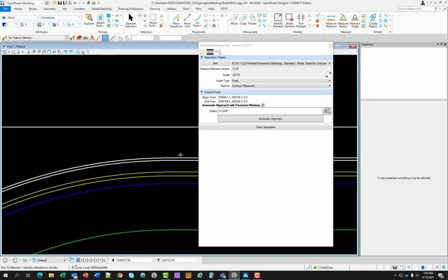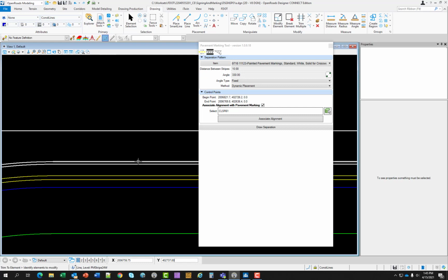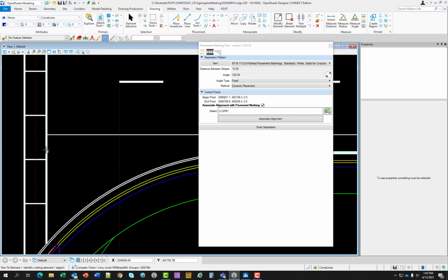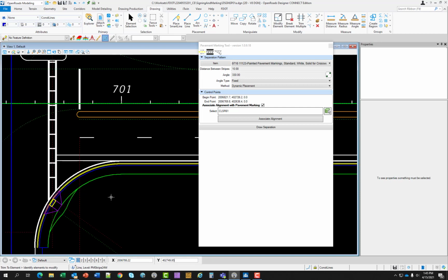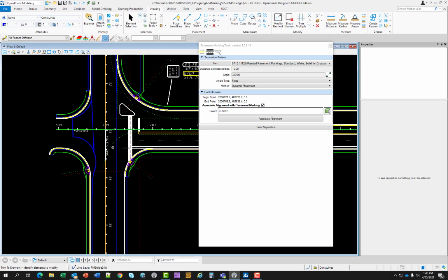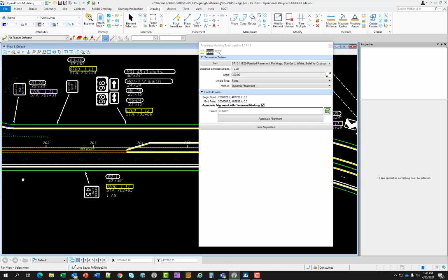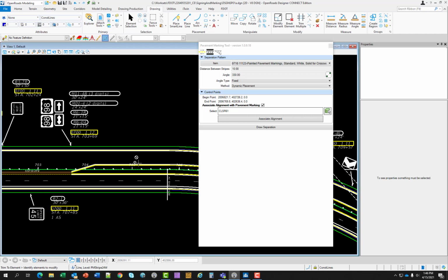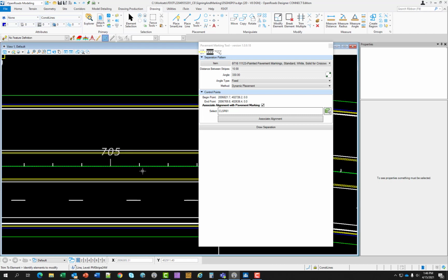First one is done. I'm going to zoom in here because I want to extend this tangent portion of that bike lane and then extend it to the crosswalk. So there we have those two items extended. So the final exercise, which is 3.7, will be adding a bike lane and 1030 skip pattern along the north side of the road. So I'm going to zoom in to